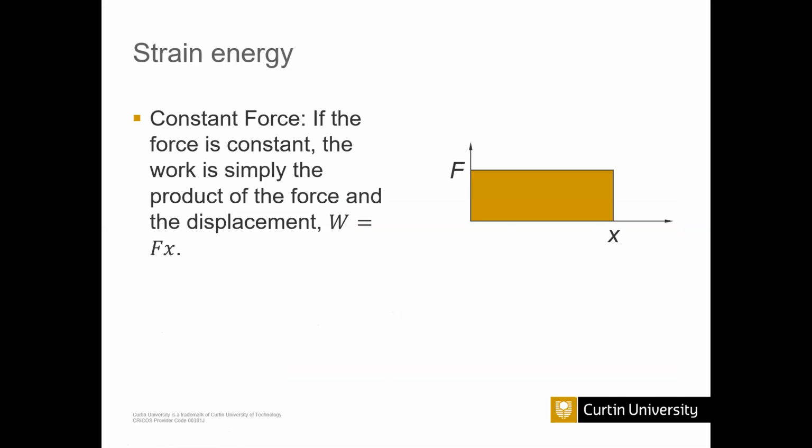As I told you, the topic is strain energy. There are different modes of load applied on the element. It can be a constant force over time. With time the force is constant, but the extension also increases. This is normally called creep. During creep failure this is what normally happens: a constant load is applied, and with time it will strain.